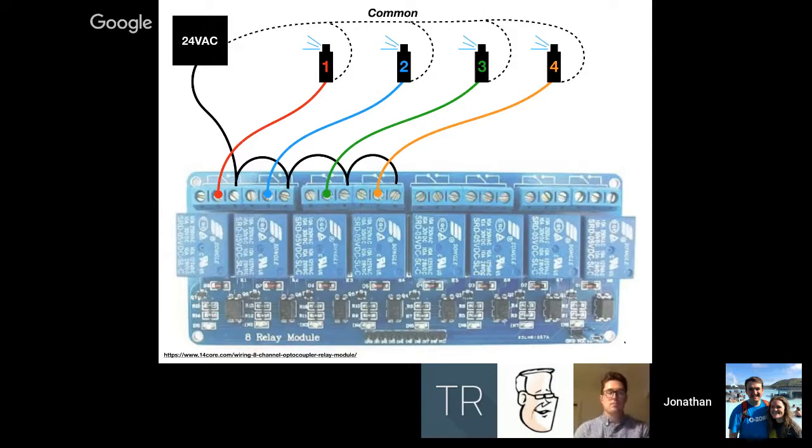Yeah. So the power to trigger and the power to hold the relays is actually totally independent. I spent probably an hour assuming that if I added power to the JVCC, it was going to power through the relays for whatever reason. But it does not. It's only for holding the relay open. These ones I think are mechanical relays.